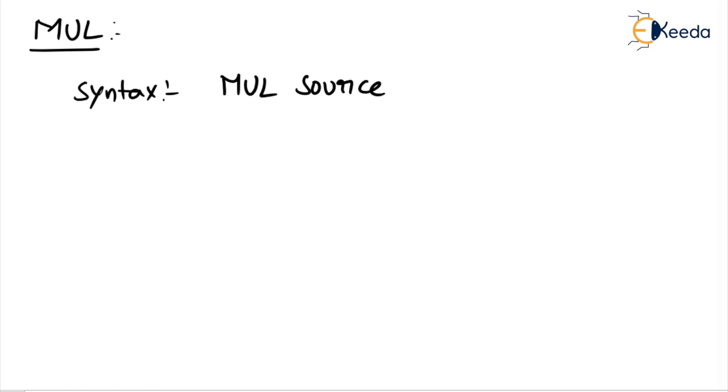If the most significant byte of the 16-bit result, or the most significant half of the 32-bit result, is 0, then the carry flag and overflow flag will both be 0. And the auxiliary flag, parity flag, sign flag and zero flag are undefined after the MUL instruction.